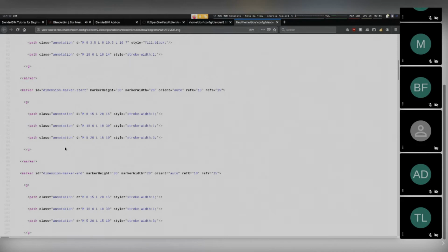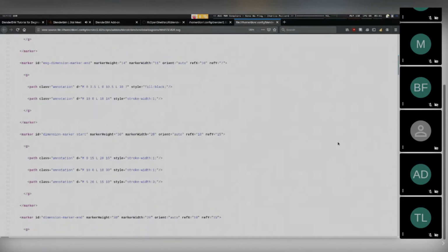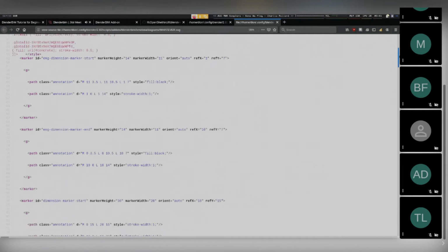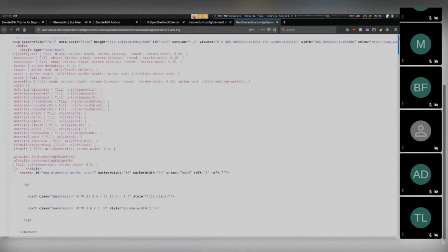And you can edit these with Inkscape and create your own funky styles. Everything is normalized to millimeters using the metric standards for hatching. So line weights are things like 0.25, 0.35 pen thicknesses, you can see there. So you don't need to do any fancy SVG math. It's already worked out for you. And if you want to do it in SVG, you just stick to these easy numbers.